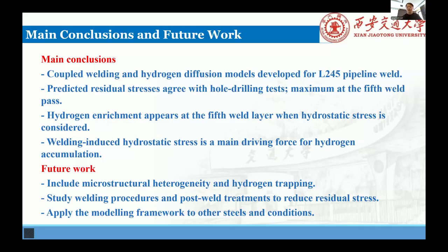Finally, the welding-induced hydrostatic stress is identified as a main driving force for hydrogen accumulation in the weld joint. For future work, we plan to include microstructure differences and hydrogen trapping in the model. We also intend to study different welding procedures and post-weld treatments to reduce residual stress and hydrogen enrichment, and to apply this modeling framework to other steels and operating conditions.